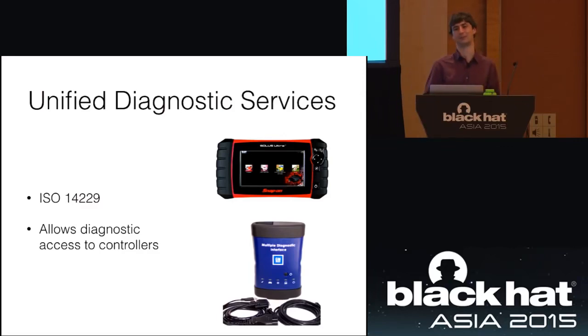But will you actually break the CAN device? No, they'll take the messages. They might overflow a bit. They might go into some shutdown state. But you can't damage the controller. The bigger concern is what the controller is actually driving.